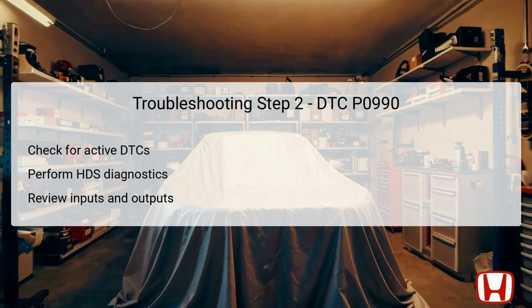In the second troubleshooting step for DTC P0990, you should check for any active diagnostic trouble codes, DTCs, using the Honda Diagnostic System, HDS. Utilizing this advanced diagnostic tool will enable you to evaluate the vehicle's onboard diagnostics more comprehensively. By reviewing the inputs and outputs associated with the transmission fluid pressure switch E, you can identify if there are discrepancies between expected and actual values.